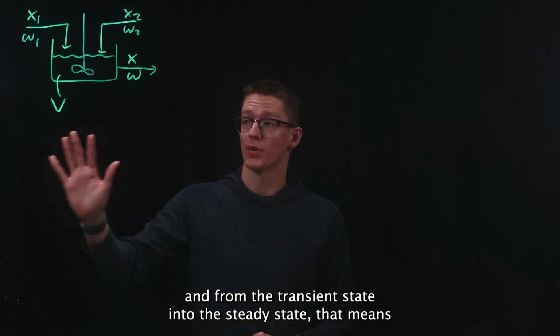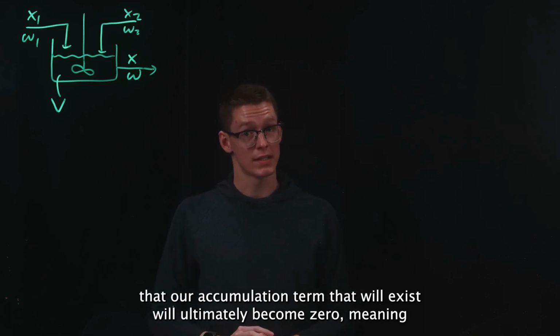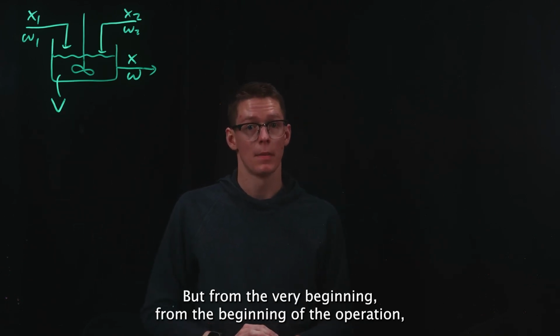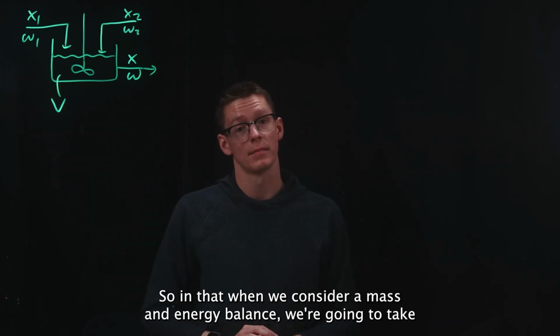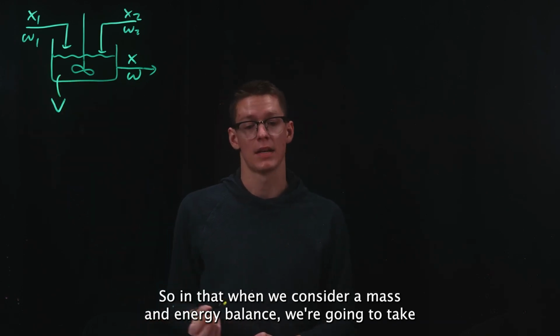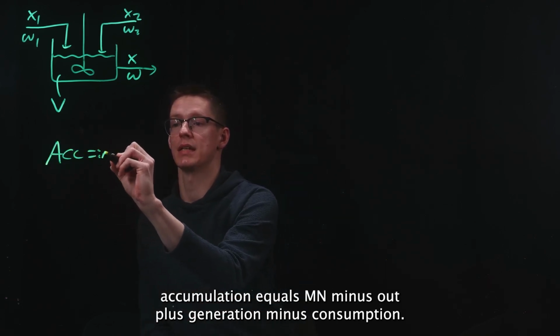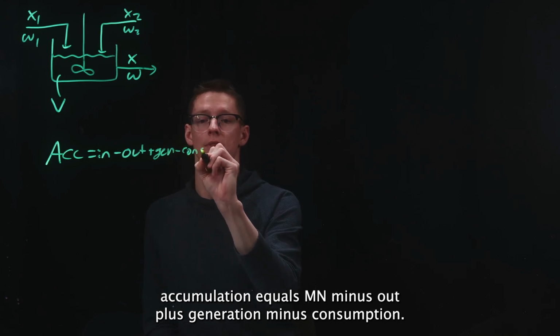And from the transient state into the steady state, that means that our accumulation term will ultimately become zero, meaning that eventually the volume of our tank will become constant. But from the beginning of the operation, we have to consider that there will be a transient setting. So when we consider a mass and energy balance, we're going to take accumulation equals in minus out plus generation minus consumption.